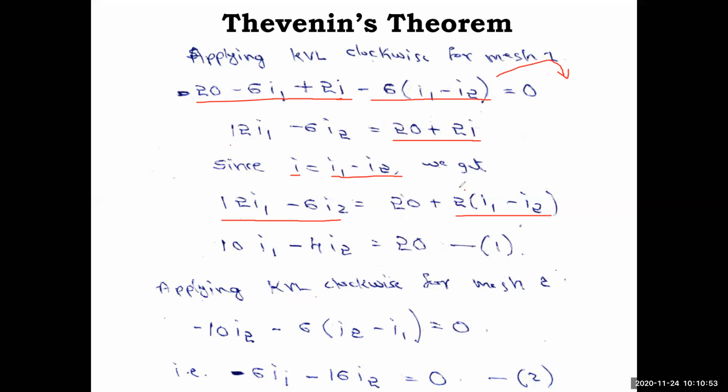and this I will take to the left side again to simplify I1 and I2. So 12 I1 minus 2 I1 is 10 I1. Straight away I have written. Okay, hope you understand this. And minus 6 I2 and minus 2 I2 is there here, so it will become minus 4 I2, equal to 20 as it is. So now the equation is clear. You got the first equation,